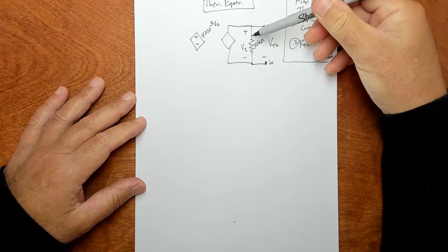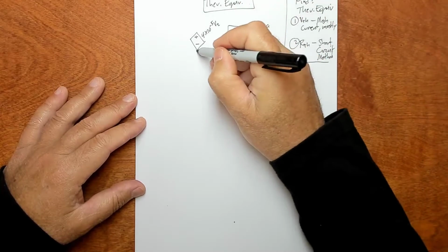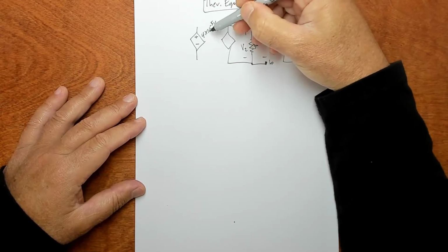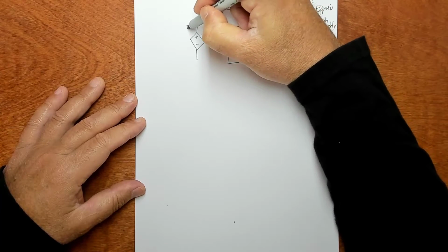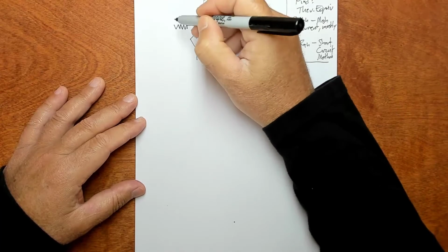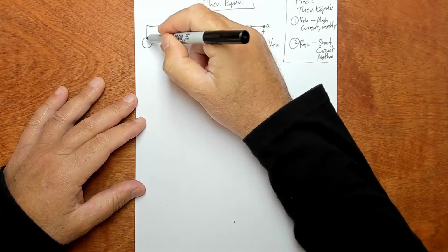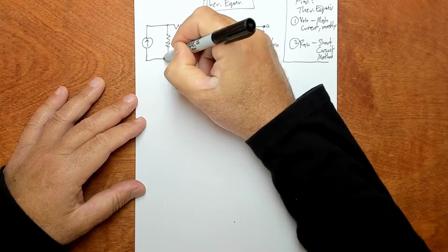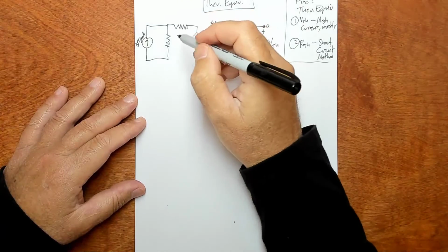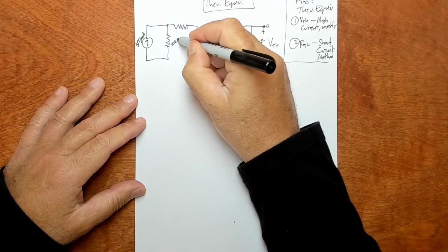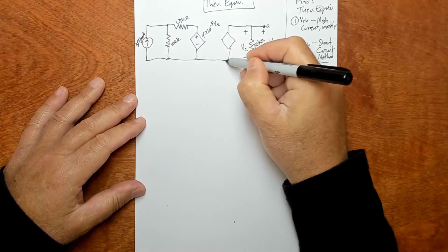So it's monitoring this reference voltage over here and putting out a proportional voltage. Very small, 4 times 10 to the minus 5 times smaller than V2, but anyway. Okay, I've got a resistor here and another resistor here, and then a current source over here. So this is a 500 microamp current source, and then a 100 ohm resistor and a 1310 ohm resistor, kind of a weird value. And these two halves of the circuit share a common ground.